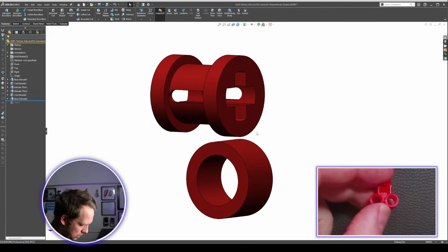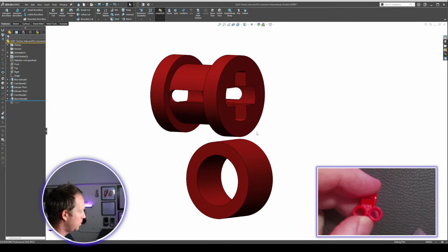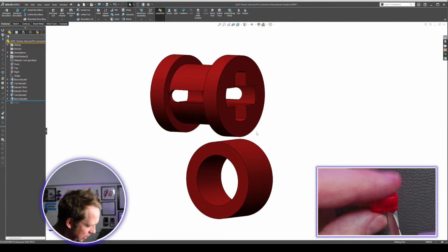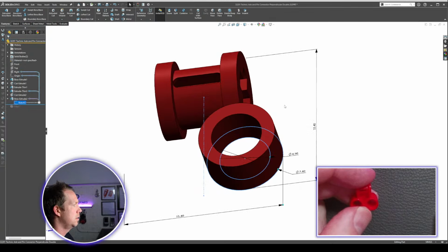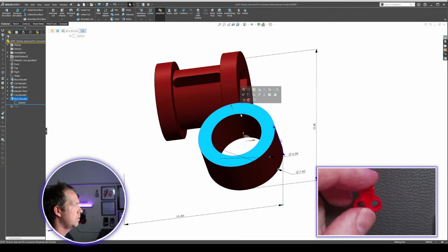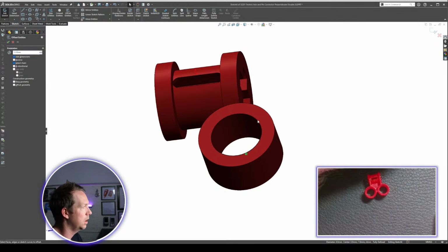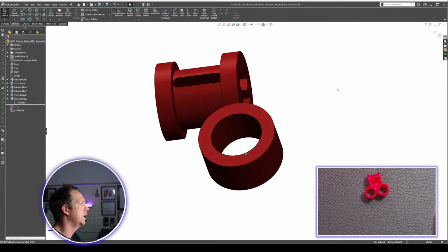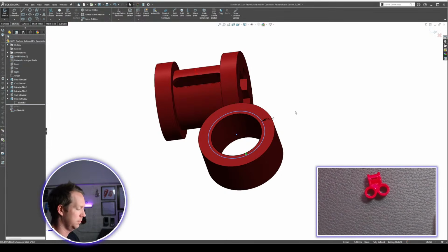Now the step down on the inside. It's too small to measure the depth of that step, but we can measure how wide it is. We can see it's 5.5. I think we can assume that it is about 1 millimeter deep. So I can convert this edge, I can do an offset, or I can sketch that circle with the dimension, because I said 5.5.